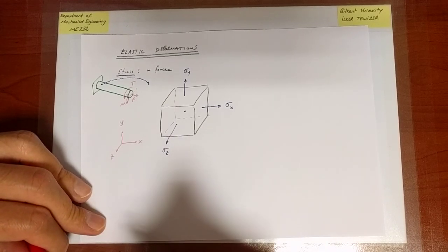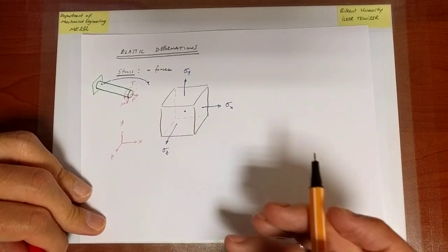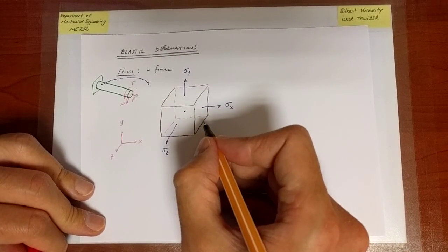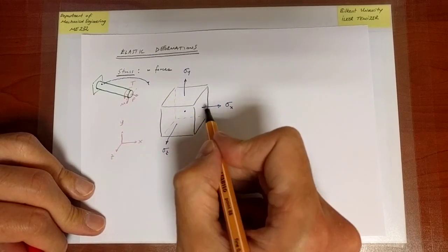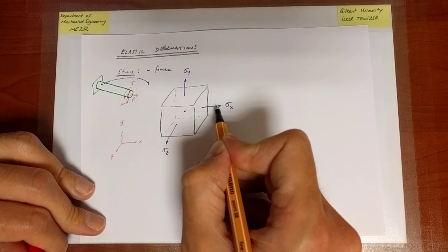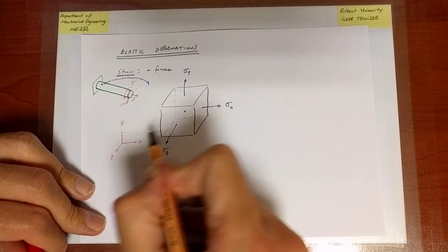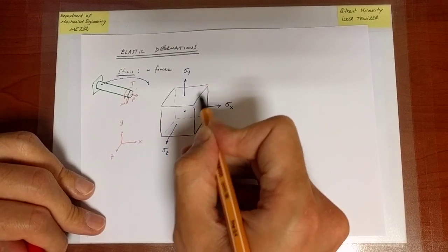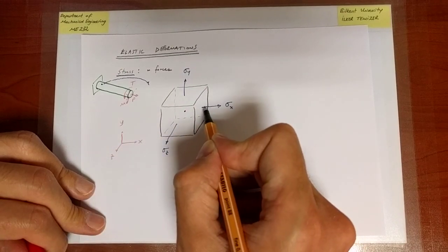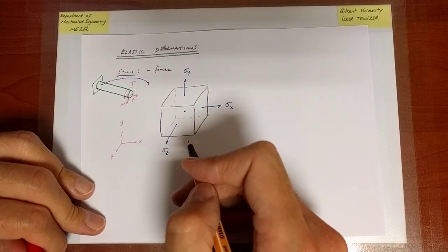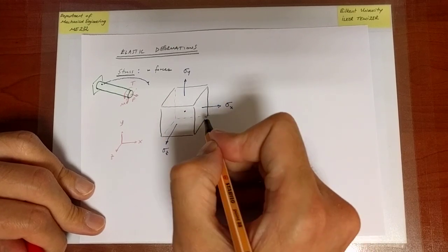Whenever I write a shear stress, we indicate it typically with tau, and the default direction has to do with, again, the coordinate direction. So the positive direction for the normal stress is on the plane with a normal that is in the positive x direction. The default direction is also sigma x.